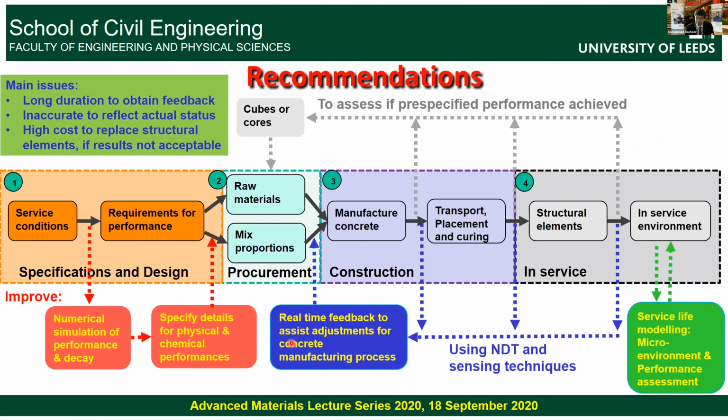Based on that, I just wanted to give some recommendations, which is that we depend very heavily on cubes and cylinders for assessing the quality of concrete in structures. That has a huge limitation. What is ideally needed is controlling the specification and design based on service conditions and requirements of performance, and using numerical simulation for assessing the performance and the decay of that performance, and then specifying the concrete mixes and the raw materials to take account of that.